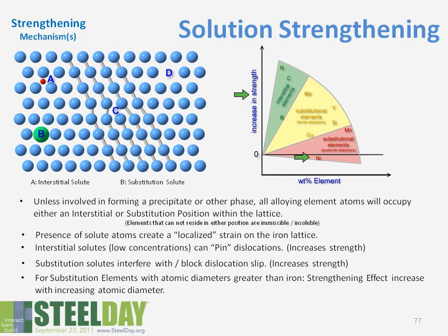It is very difficult in an alloy if I have more than two phases to predict the behavior. So if I can simplify that down to just a pure iron and carbon alloy, I can more easily predict its behavior. So that's what carbon equivalency attempts to do. I don't know if that's a sufficient answer for the person asking.